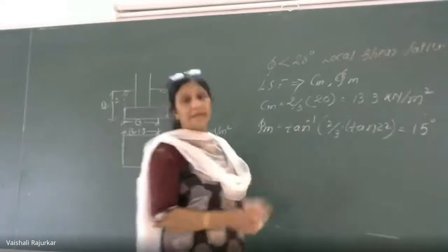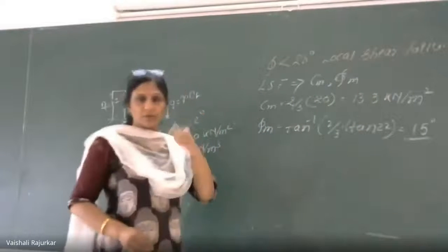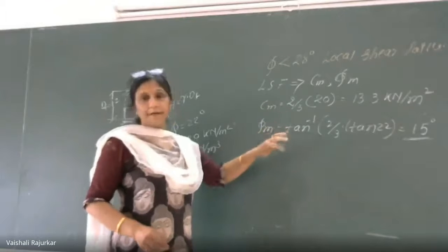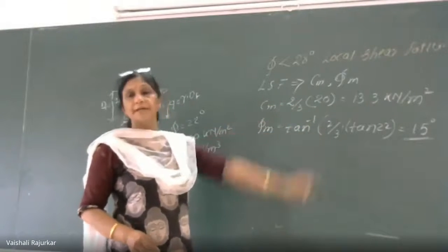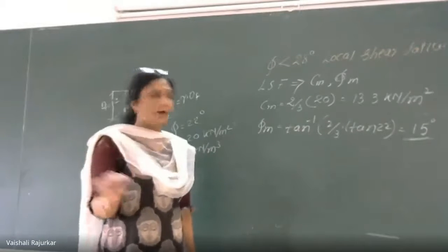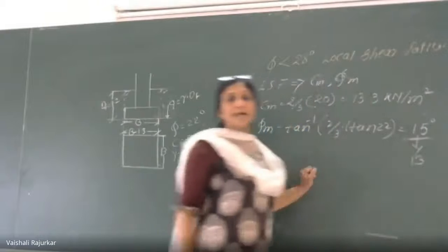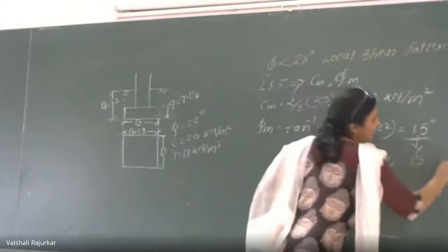Here the value for 15 is directly obtained from the table I gave you in the previous topic, with NC, NQ and gamma values for 15. If it is not, suppose 13 comes instead of 15, in that case you have to interpolate between 10 and 15.